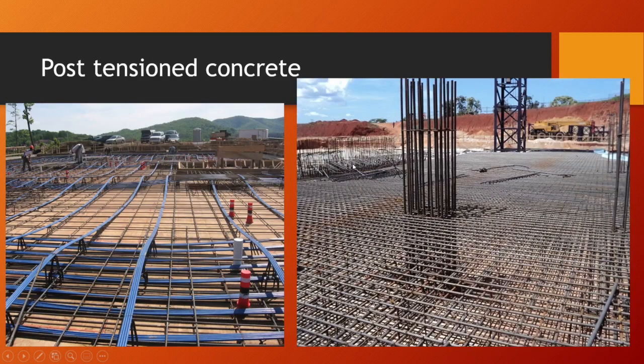Okay, this is post tension, and this is something that I looked at in the previous recording. I've done a lot of this on motorways, it's what we call steel fixing. So you can see the steel rebars like that, and they're all connected in mesh on what we call beds and mats, and they're all tied together usually with a stainless steel wire. And then we can see that these are going to be columns that are going to be projecting from the main slab, a foundation main slab.